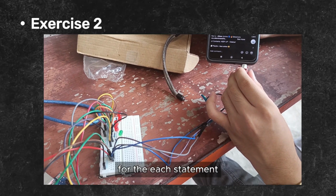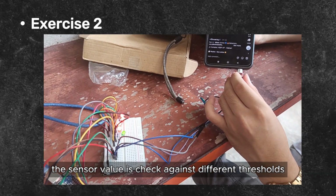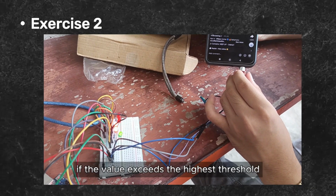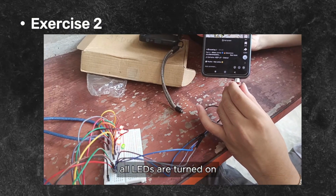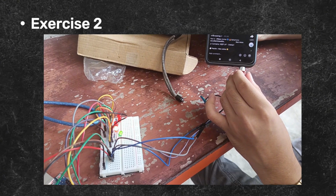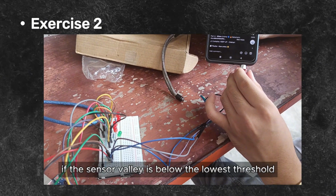For the if statement, the sensor value is checked against different thresholds. Depending on the value, a specific set of LEDs will light up. If the value exceeds the highest threshold, all LEDs are turned on. As the value decreases and falls within the lower threshold ranges, fewer LEDs are lit. If the sensor value is below the lowest threshold, all LEDs will remain off.